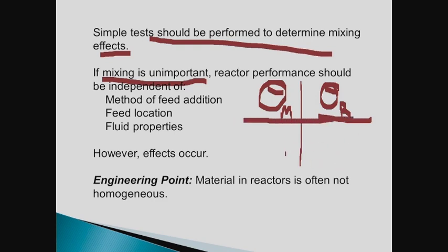However, if the reaction is fast, then you find out that the mixing time may equal the reaction time. As soon as the thing is mixed, it reacts. So that would mean that the mixing time and the reaction time are the same. So you have a whole slew of situations out there, a whole gamut. This is often expressed as a Damköhler number, the ratio of transport time to reaction time.